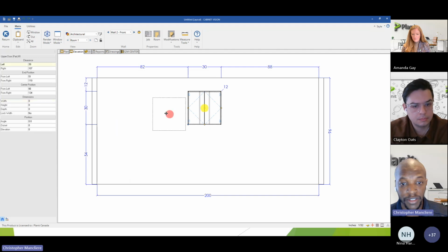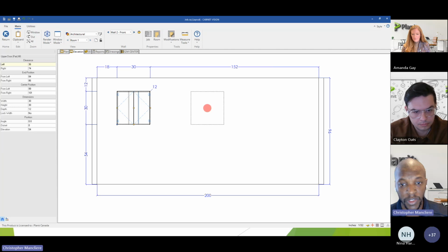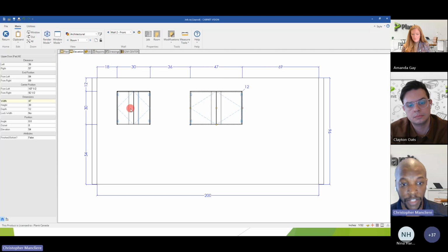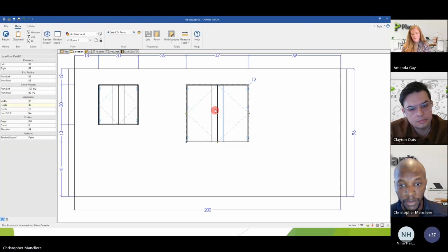Then what I do to test it, I simply copy the original assembly and make some modifications on the copied cabinet. So I know that if it's not working, I forgot something, I can go fix it on the original one. So what I want to check is to make sure that this is still in the center of my cabinet. This is also resizing all my parts.